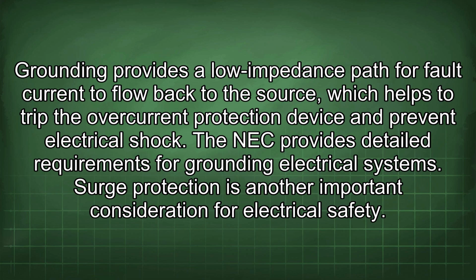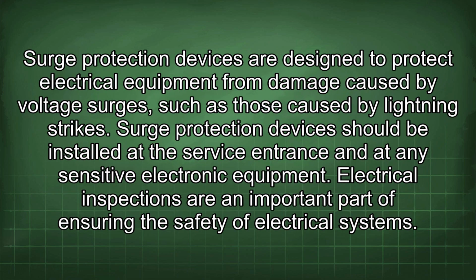Surge protection is another important consideration for electrical safety. Surge protection devices are designed to protect electrical equipment from damage caused by voltage surges, such as those caused by lightning strikes. Surge protection devices should be installed at the service entrance and at any sensitive electronic equipment.